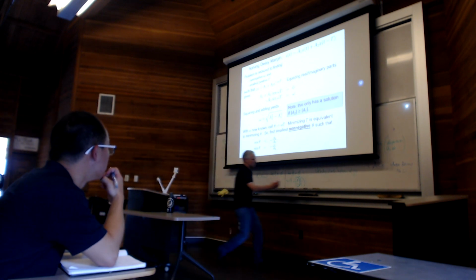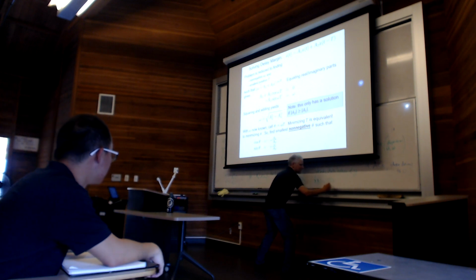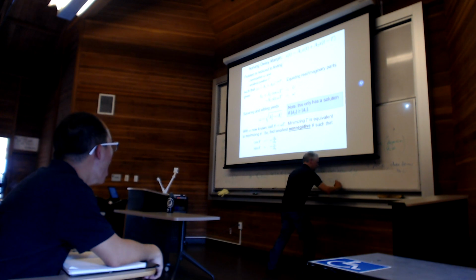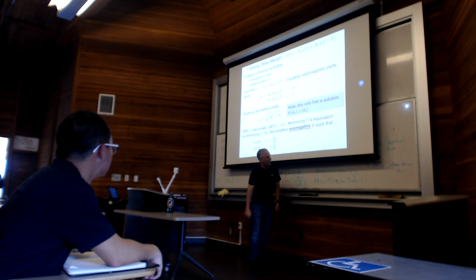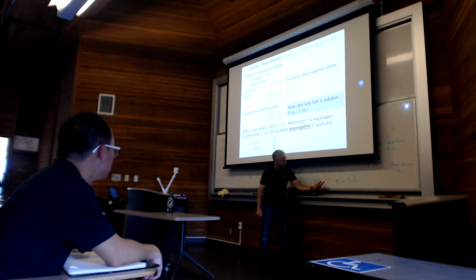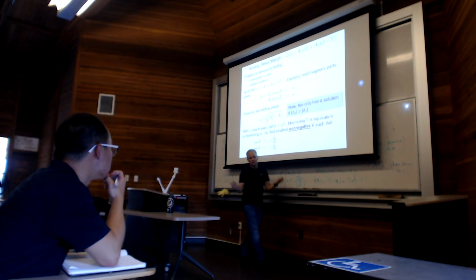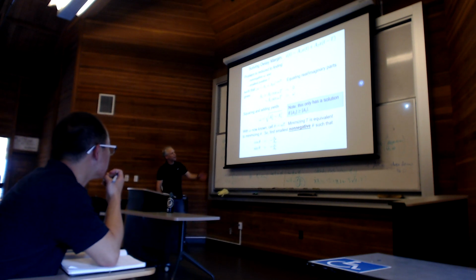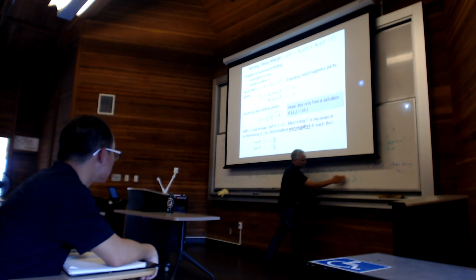So if we had a system that looked like this, x dot equals negative 5x(t) plus 3x(t minus tau). That's one where a1 plus a2 is negative, so it's stable with no time delay, and a2 is smaller than a1, so that'll never go unstable. But in general, if a2 is bigger than a1, so the example that I threw up there, which was more like this,